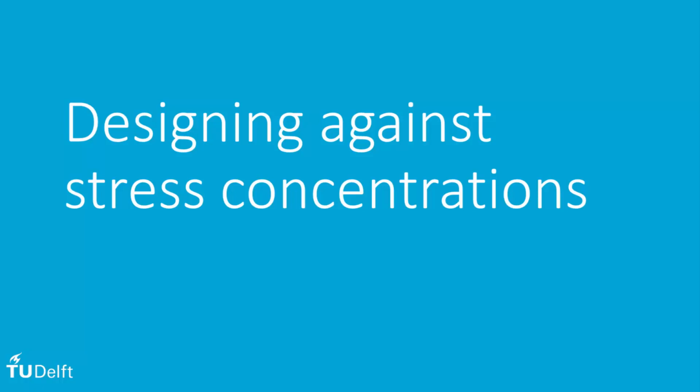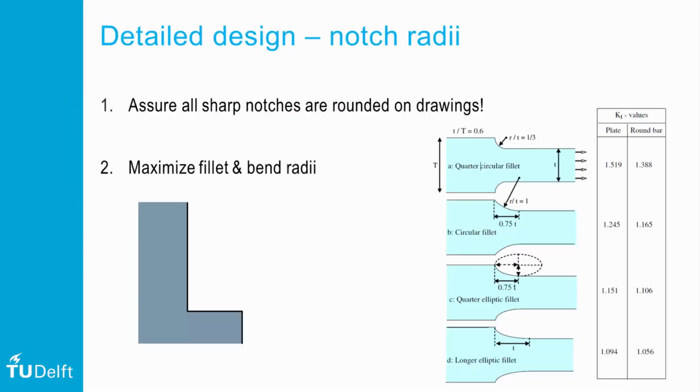So what are the steps we take in detail design against stress concentration factors? First, we have to assure that all sharp notches and corners are rounded on drawings. Sharp notches mean by definition high stress concentration factors.